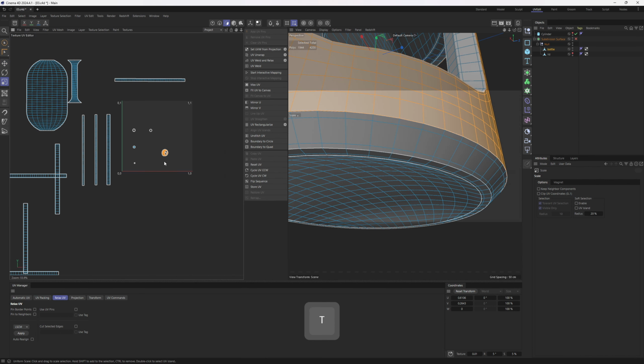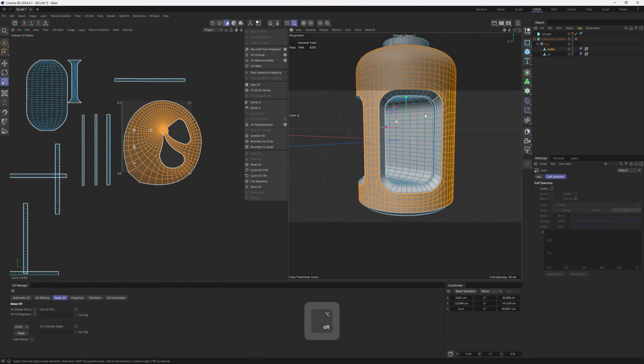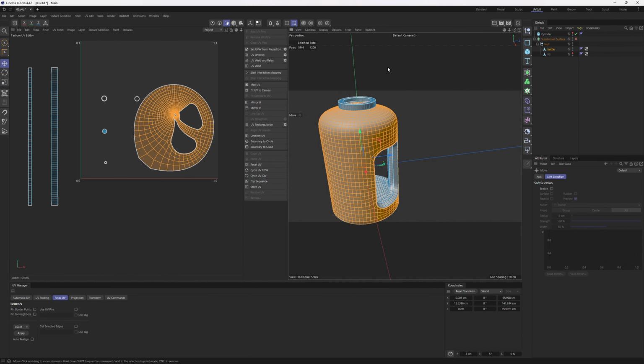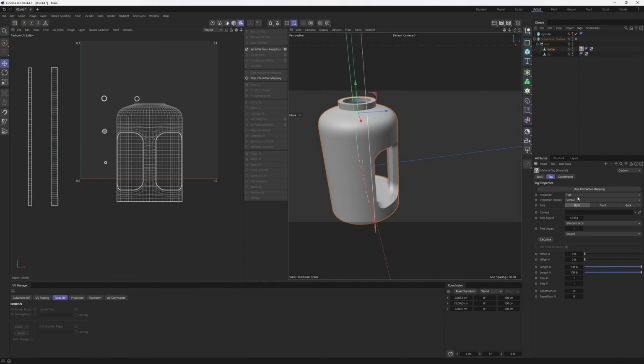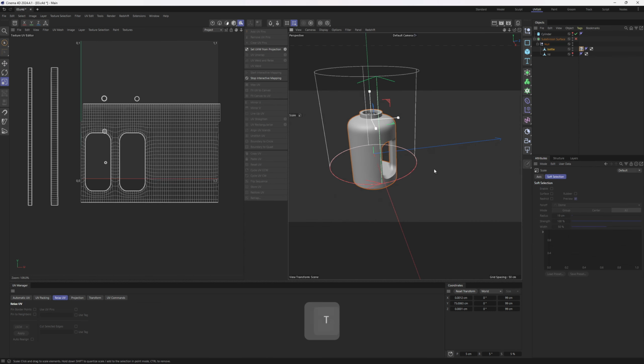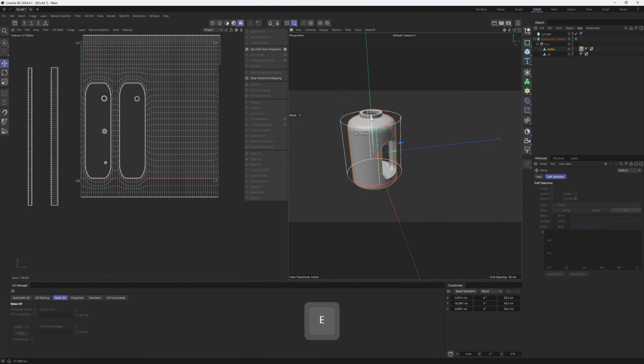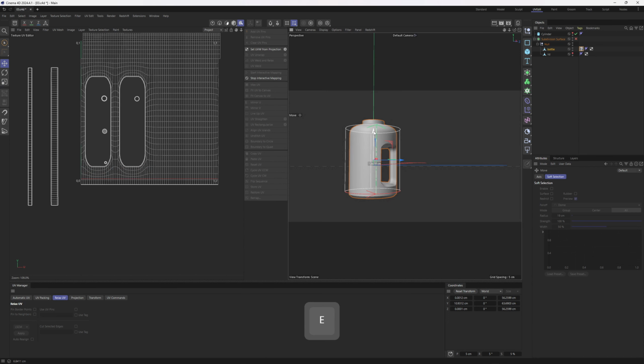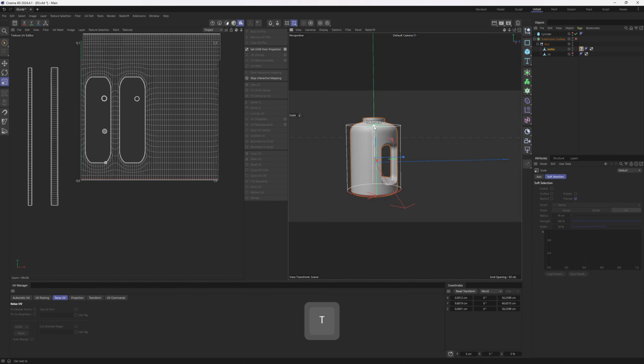Let's bring up the big boy. This is the most important UV island we need to work on because this is the part that we will texture on. Whenever you have this kind of cylindrical bottles, just use interactive mapping tool, which is just perfect because it has this cylindrical projection option. Scale that down and adjust the size. It doesn't have to be perfect.